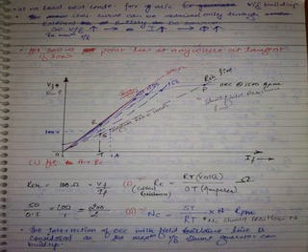Only three steps. Plot OCC, plot the field resistance line, plot a tangent to OCC. Finished. Somewhere here, make a point R. Drop a perpendicular. It will cut the field resistance line at a point S. This is T. RT represents the rated speed, the given speed. ST always represents the critical speed only. This length represents the critical speed.